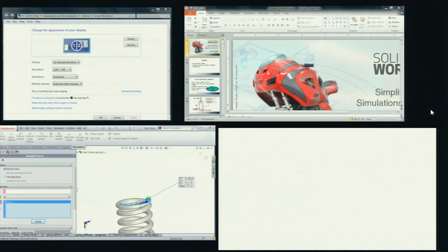Do you have a question? How did you restrain that in lateral? When you did the lateral, how did you restrain it to make sure it worked? Well, I applied 2 boundary conditions to the top surface. I applied a 1 millimeter tangential displacement and also a roller slider on that flat face. So that keeps the distance straight. You're just moving it laterally, not like this, right? And the bottom's fixed. I didn't mention that.